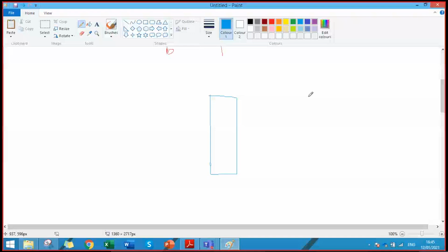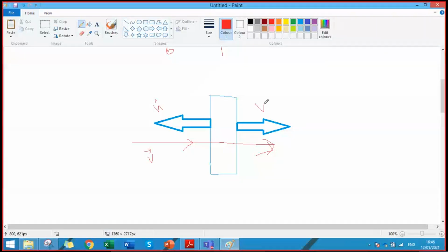In this case, this is a two-dimensional body and there is flow across it. The area normal of this left surface will be pointing in this direction, and the area normal of the right surface will be pointing in this direction, right? Yes, sir. If we have flow from this side to this side, here the area normal n vector is anti-parallel to the velocity vector, right? So v dot n would be negative for inflow. On the right side, v and n are parallel, so v dot n would be greater than 0. Clear?